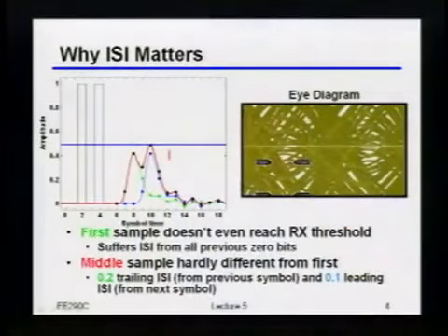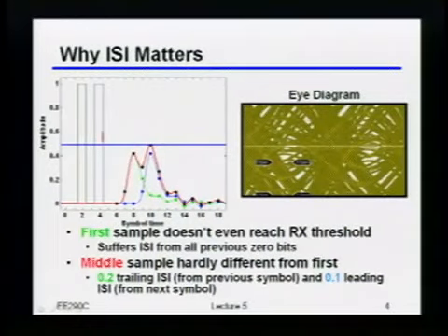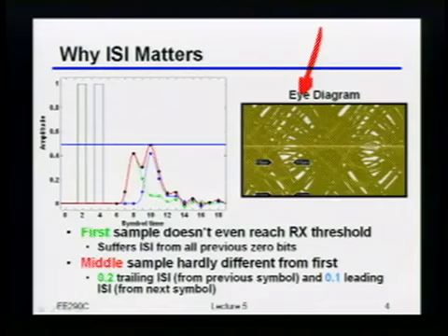Okay, so the point here, again, is that you care about what the channel is actually doing to you. Of course, if you had something like this, and you can look at this in the eye diagram as well, you can see if I took my pulses and passed them through this channel, my eyes are completely closed, right? I can't tell what is a 1 and what is a 0. I have no margin. I'm just going to get errors all over the place.